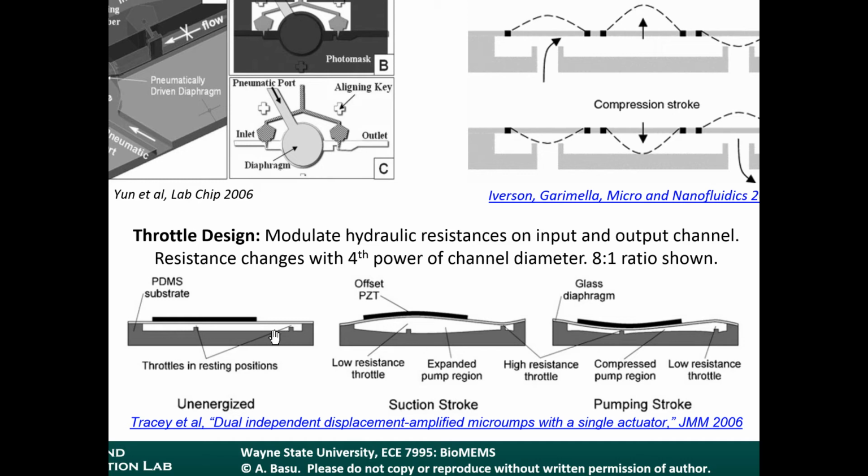Okay. Now a key concept in here is that the piezoelectric actuator is offset. It's not in the center of the membrane, it's really off to the side. That's what creates this asymmetric motion. This asymmetric motion opens up the region below this throttle during the inlet stroke, and then it closes this region off during the outlet stroke and opens the outlet region.